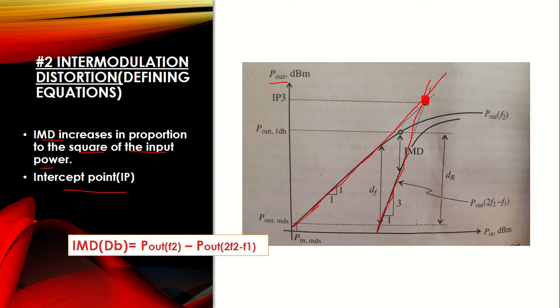The use of finding out this intercept point is, using this point, if we trace back down the graph, we can identify the regions of your original spectrum as well as your distorted spectrum. So on finding the intercept point, we trace down the line to obtain what might be the original spectrum of the signal as well as what might be the distorted spectrum of our given signal.